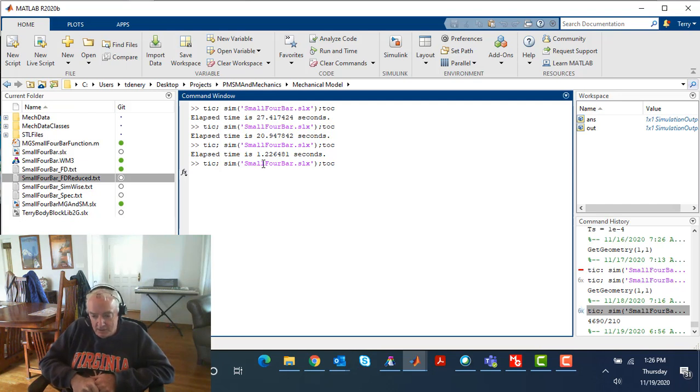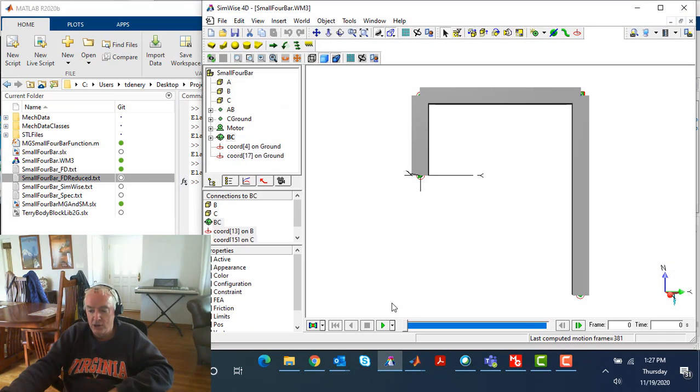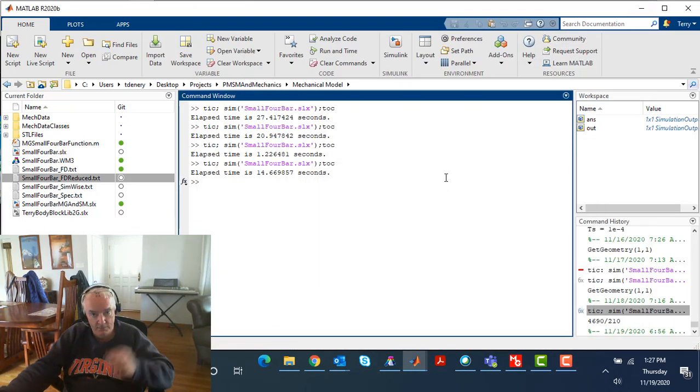And so we're going to see, again, there's this really important speed advantage available through the direct solution to the differential equations. I'm happy to show this at this point without feeling I'm diminishing the usefulness of Simscape Multibody. What I'm showing here is the complementary nature of the two solutions. The mere fact that they're both coming from the same general mechanical description defined in the SimWise model, and that they predict exactly the same results for this problem, means that they are equivalent solutions relative to accuracy.